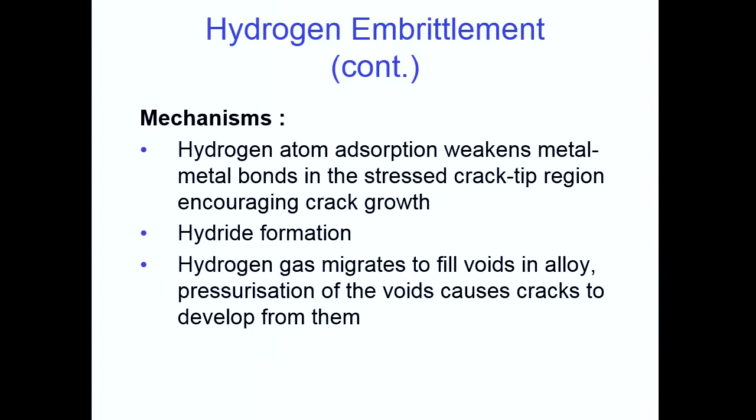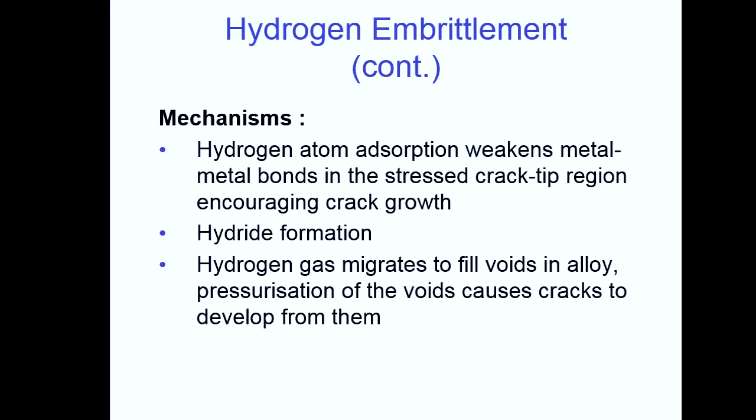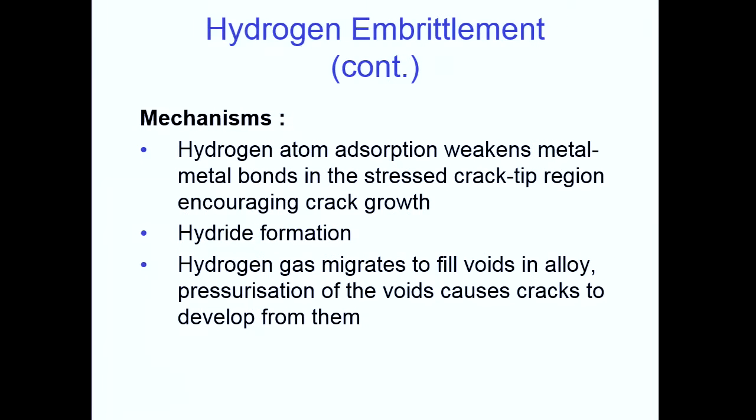And so there's some equilibrium of migration, diffusion through here. Remember, the hydrogen moves very fast through the material. So although this theory has been put forward, and there probably are some interesting bits of evidence, what I'm struggling with is the equilibrium between the partial pressure outside and the partial pressure inside.